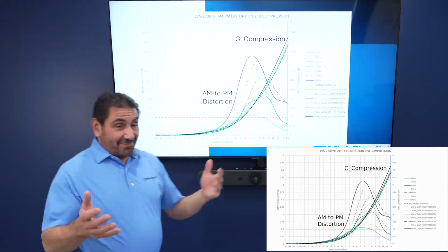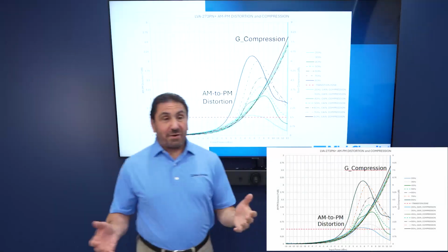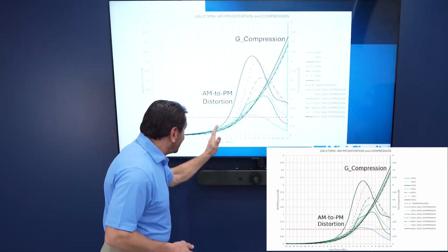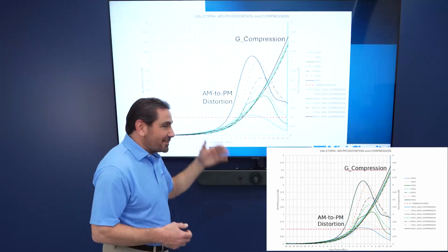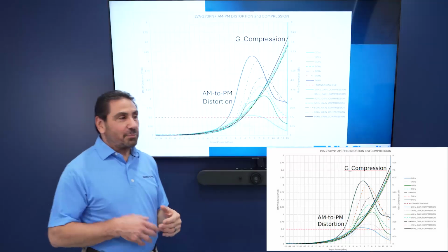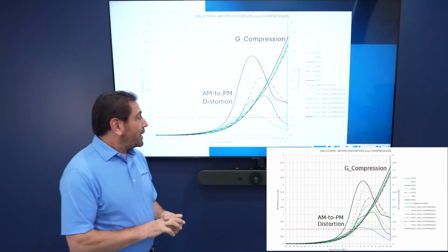And that's really the system designer's responsibility. Can I operate at 8 dB compression? I don't know, you've got to tell me. Can I operate over here and only get that much output power? If I put in 0, I get +15, is that enough? If I put in -3 and I get +12 dBm out, is that enough? I don't know, it's up to you.